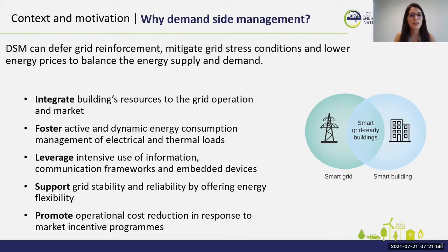So how does demand-side management work? It basically integrates building resources to the grid operation and market. It can be the loads, or it can be the on-site generation. It fosters active and dynamic energy consumption management, be it electrical or thermal loads, by leveraging the exchange of information, so the use of information and communication frameworks, and embedded devices, that is sensors, actuators, and controllers.